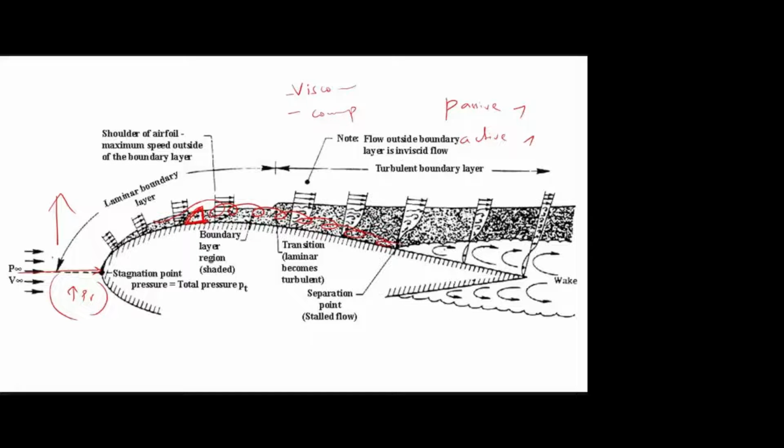Vortices mean in the center it will have low pressure. The vortices will have low pressure in the center. So this shape is mainly to produce the axial vortex. That means a low pressure region, and this low pressure region sucks the separated flow. For example, if the flow separates from here and you place this vortex generator, it will create the axial vortex. That means a low pressure region that sucks the separated flow so that it will be attached up to a further distance. The detailed discussion we will do in the 5th unit. So this is about flow separation, separation point, wake, pressure drag and all.